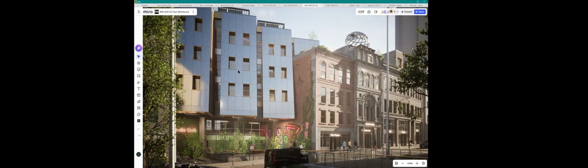If you look on the cover page, I thought I had it. Oh yeah, like one of these renderings. This is what it looks like, and you say, "Oh, that's a nice modern looking feature." These are actually solar panels. But as we're talking about Revit features, curtain walls were used to do this, right? In this case, these are not glazing, but you're still using curtain walls. So I'm showing you this to say that you can use curtain walls to do other things.